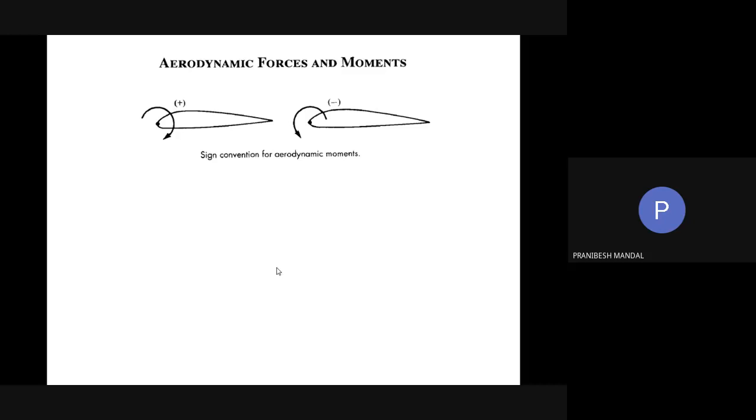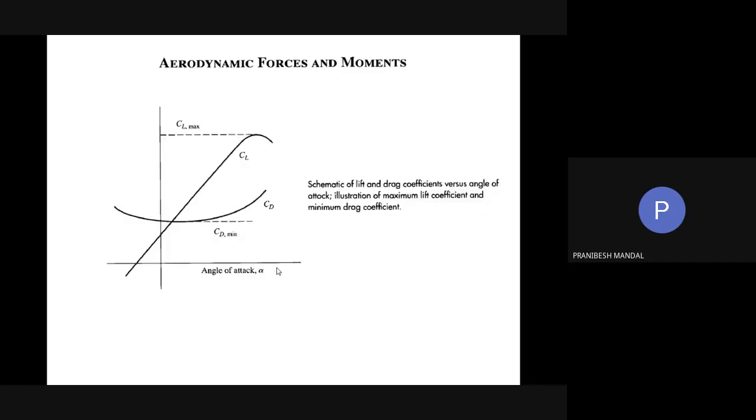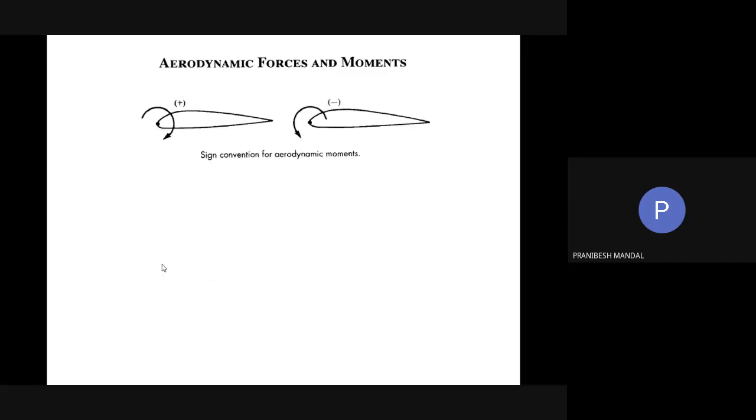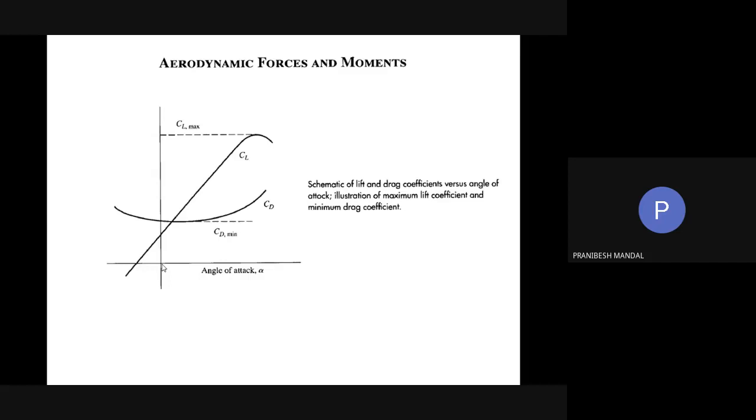If those two surfaces are symmetric, that is for a symmetric aerofoil, then CL will be zero at zero angle of attack. As there is an asymmetry in the design for airplanes, that is why there is a small positive CL even for zero angle of attack. Okay.